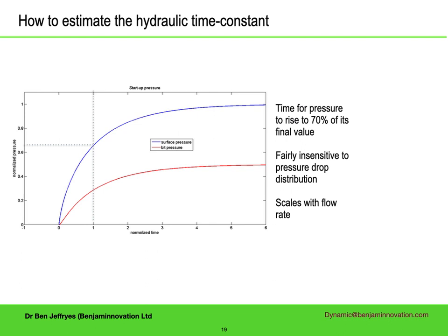The most important parameter in the fluid system is the hydraulic time constant. It depends on something that is quite difficult to calculate, namely the average fluid compliance. Luckily, it can be estimated quite well from the data. Looking at the time to zero on pumps off is very error-prone. The gradient of the pressure curve is very shallow as it approaches zero, and then the fluid flow goes non-turbulent, or some rig activity will perturb the system.